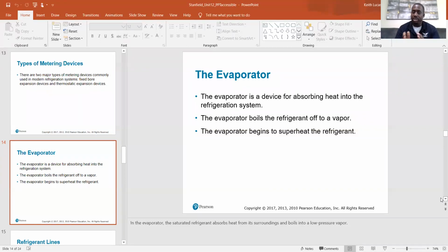So our heat transfer is going to take place. Heat energy goes from hot to cold. So that hot air that just got sucked in is now getting all the heat energy absorbed from it to the cold refrigerant in that coil. So it's coming out of the other side as cold air. That same hot air that just got sucked out of the room is coming right back into the room, but minus all of its heat energy. It all got sucked out. It all got absorbed by that 40-degree refrigerant that's in the evap coil.